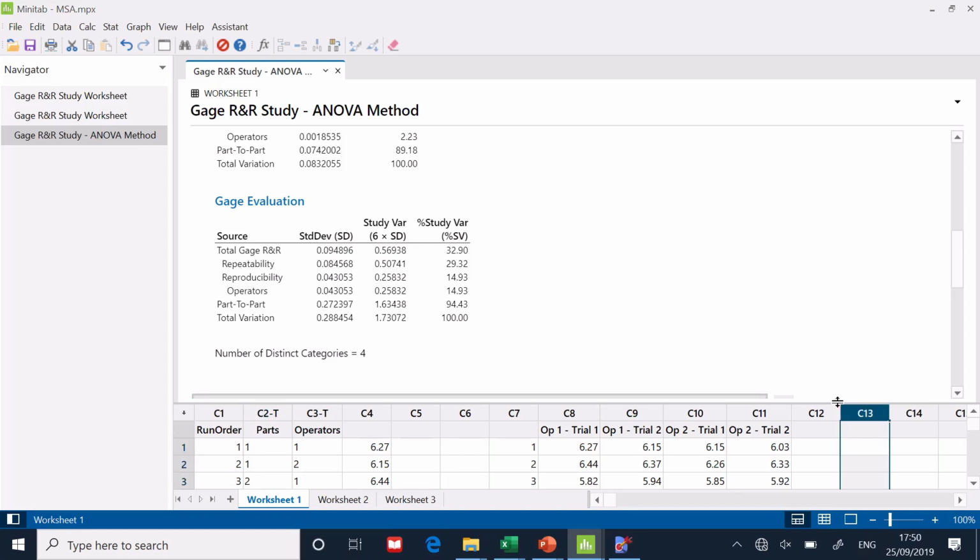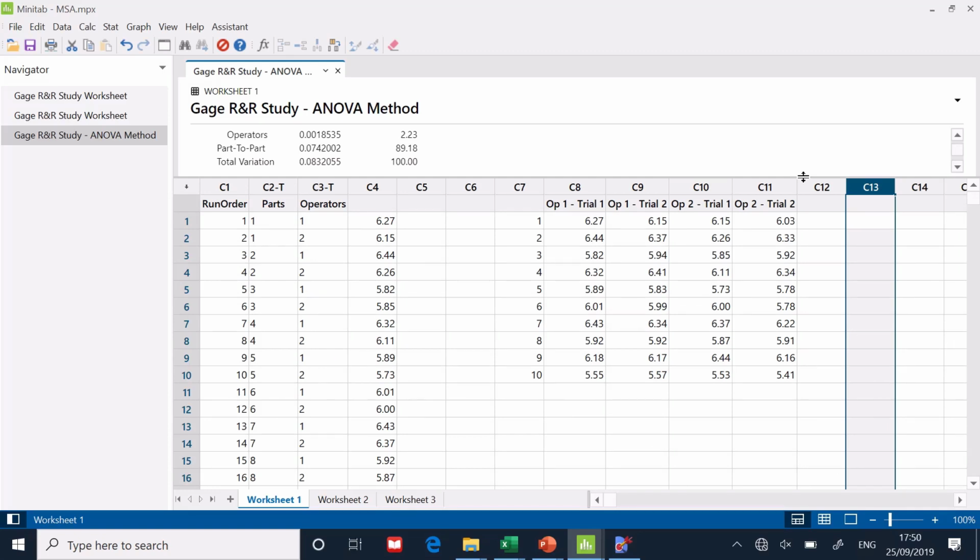Now, if you look at the results here, if I just get the results table up and just use your common sense. So what we're talking about, look, is the errors there. We're not getting agreement within system. So both of these systems, look, they're struggling to repeat their measurement. There was quite a large millimeter difference there. There's quite a large millimeter difference there. That's much better. That one's not too bad. Some of these, look, nearly a quarter of a millimeter difference. So they're really struggling to repeat their measurement. That's where most of the problem lies.